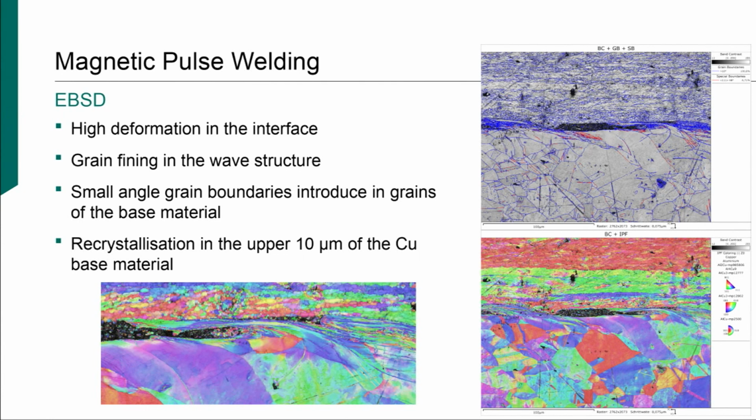All these pictures use different types of evaluation of the EBSD data. You know EBSD? It's, as the name says, electron backscattering diffraction, so it allows you first of all to determine the orientation of the different grains. So the colors just give the orientation of one grain. Here you see this color code, so red is 001 and so on.